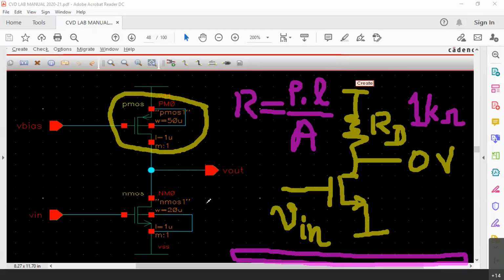But now we are thinking about common source amplifier, which is inside the chip. And in our case, the resistance will not be in the range of mega ohms. So we can simply replace the resistor with the MOSFET, because the MOSFET works like a resistor in the linear region. That is the point here finally. Instead of wasting this much of area for a resistor, simply use a MOSFET, because MOSFET is simply a source and a drain and a gate. That's all. MOSFET will be much smaller than the resistor in this case.